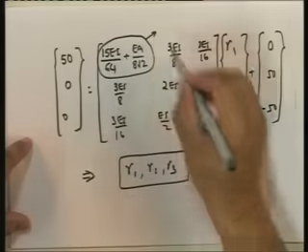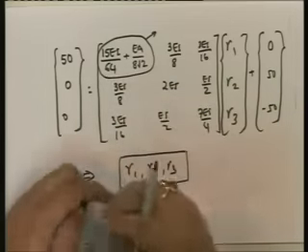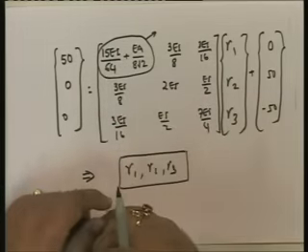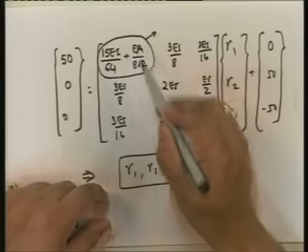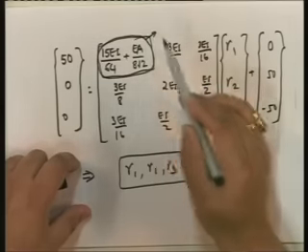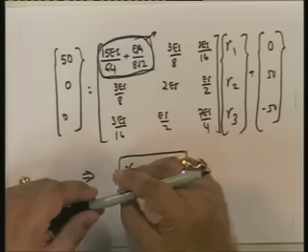You will see that the stiffness value that you get is essentially overpowered by the value of the bracing. Okay? And in fact, that is the whole point. The point why the bracing is provided is to provide lateral stiffness, and that's where it is provided, because R1 corresponds to the lateral motion of the structure.